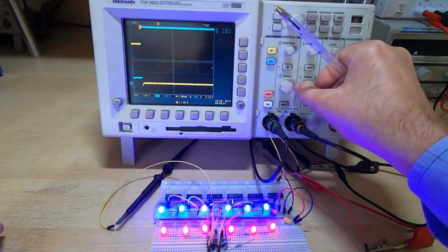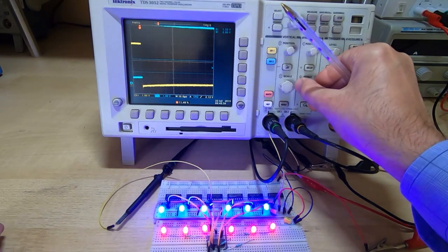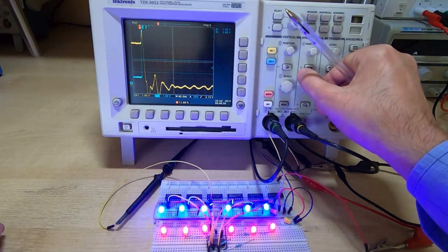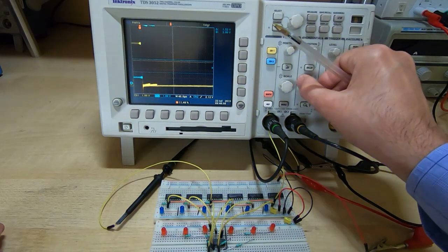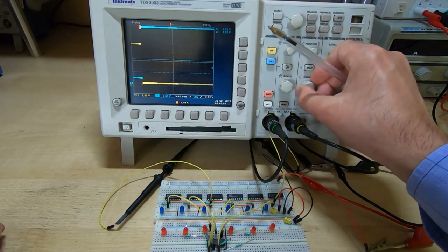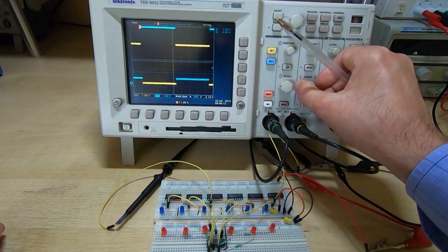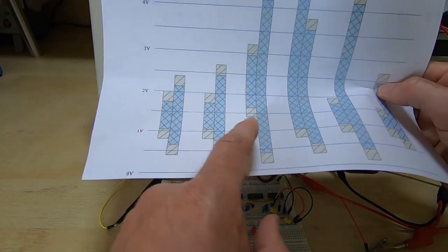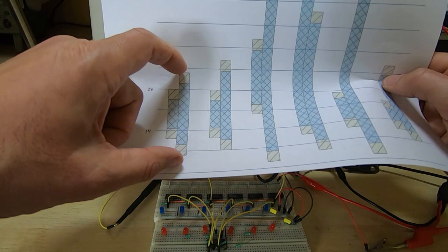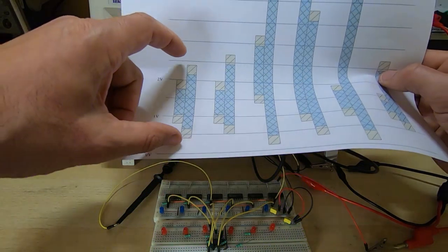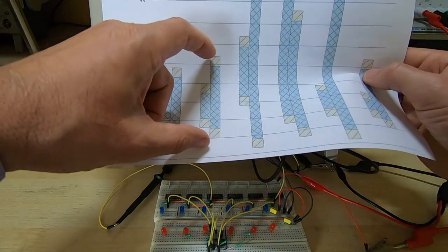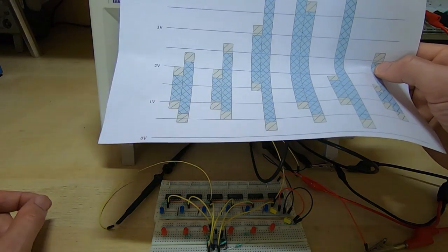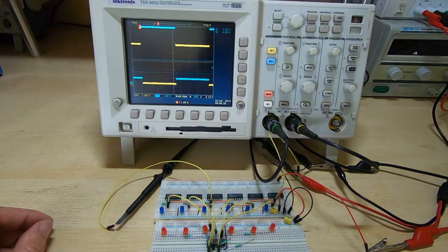If we look at the edges, you can see we get nice sharp edges, and they're switching in just a few nanoseconds with some bounce. Other than that, they're looking quite reasonable signals. What I'm going to do now is change the setting for the input signal to the various different types. I'm going to set the input to all the chips, in turn, to the expected output values of each type of chip, as if in the first instance a 74 series TTL chip is feeding them, and we'll see what the effects are.